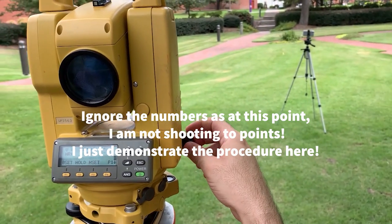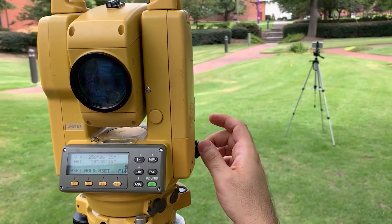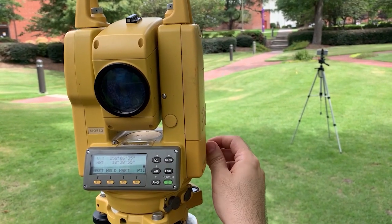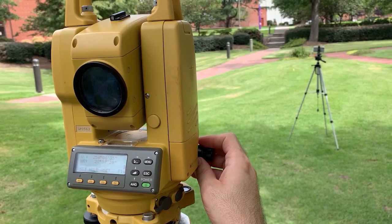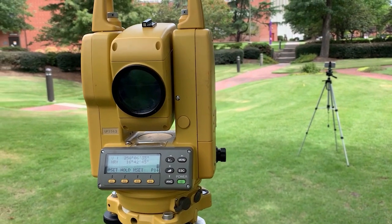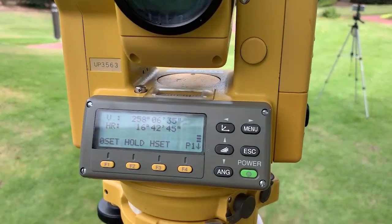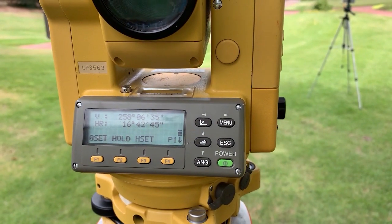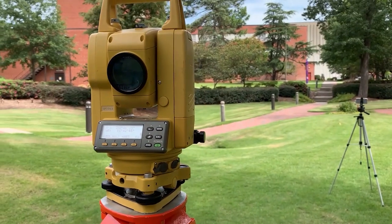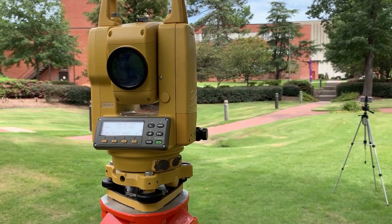If you lock it, only the minutes and seconds would change. And you read the horizontal reading, or horizontal angle. When you shoot to the first point, set to 0, then shoot to the second point, it will be your single angle.